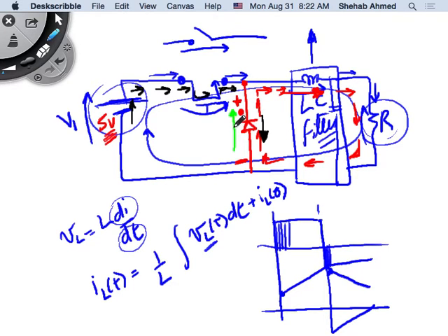The ideal switch is on, and this is a high impedance path. Where does current like to flow, through a high impedance or a low impedance path? Low impedance path, right? So current will flow through the diode in this case, because it's still on. It's not able to block. So it will do this negative current thing that the characteristics require for the depletion layer to be built up again and the diode to start blocking, right?